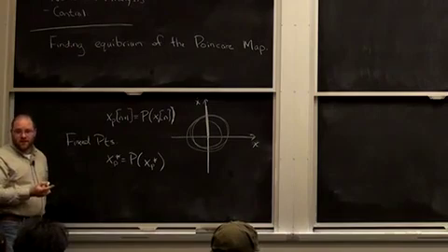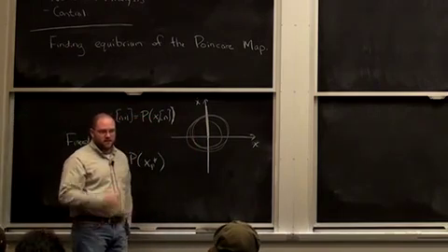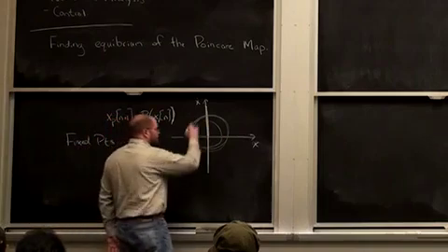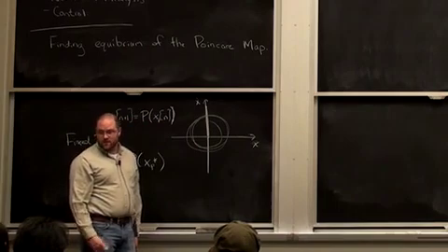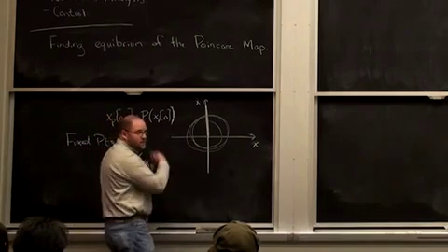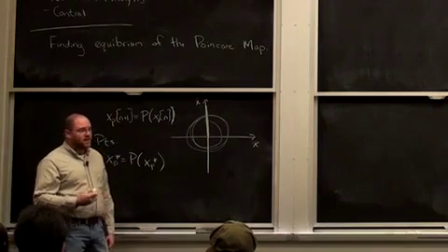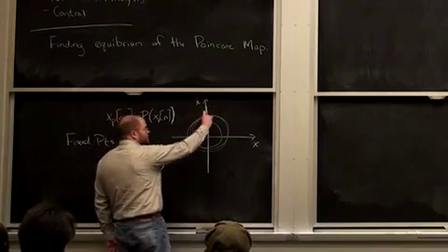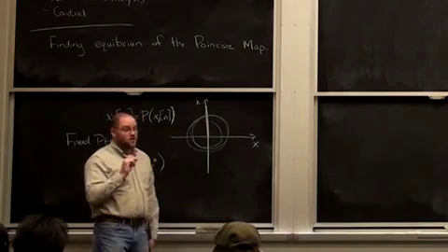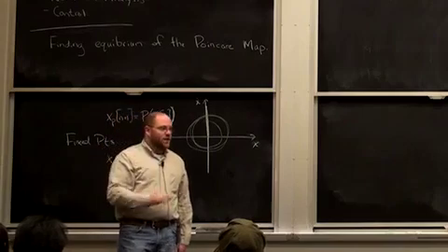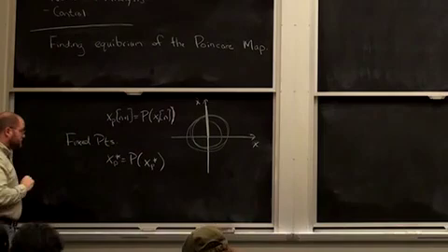If it was stable, then you could imagine finding the fixed point, for instance of the van der Pol oscillator, just by simulating it for enough time. It'll eventually find its way to the stable fixed point if you just run it long enough. But if it's unstable, that's not as easy to do. And for systems like the compass gait, the basin of attraction is small enough that you could spend a long time trying to find initial conditions which happen to simulate their way into the stable fixed point. So we want to get some better tools.